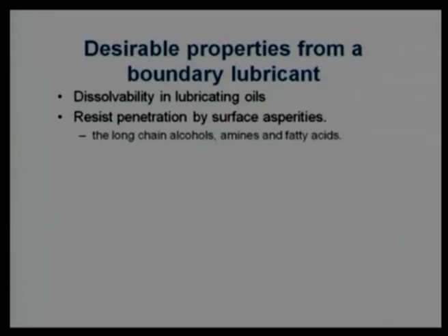If the asperities are able to penetrate the other surface, then wear volume and wear rate will increase. That is why we prefer to use long chain alcohols, amines or fatty acids for physical adsorption. These three are for physical adsorption; chlorine, phosphorus, sulfur are for chemical action.